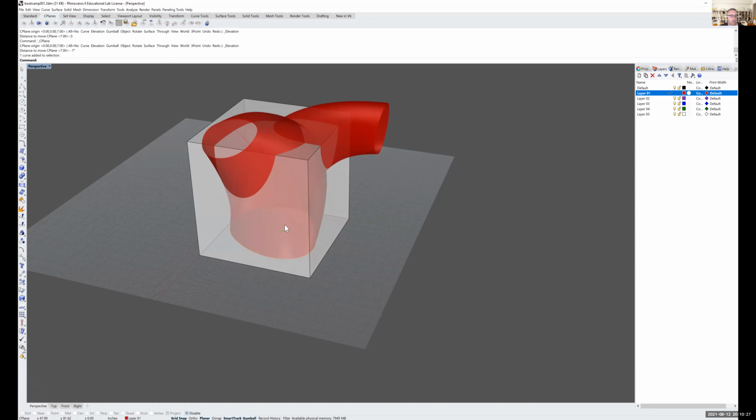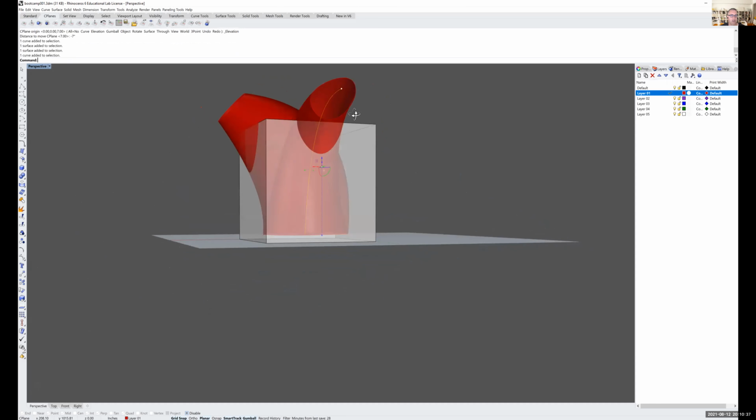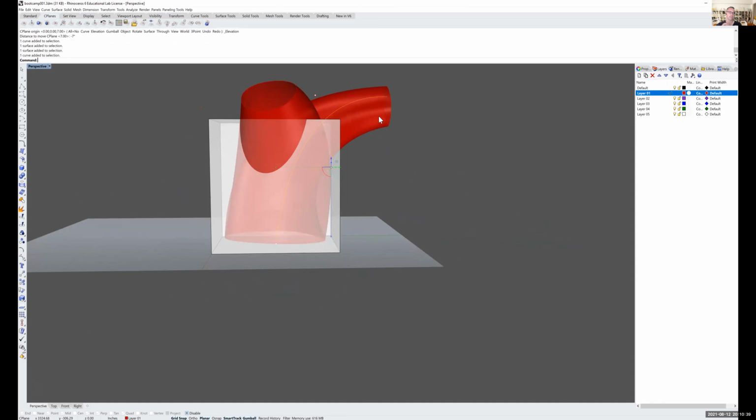And my trick too, when we start and we draw this kind of curve, not that curve, this curve, right? My trick of drawing that curve in elevation then just allows us, rather than elevating the construction plane based on a relative number, to just set the construction plane normal to that curve along its length. So it's just different ways of setting some of those things.